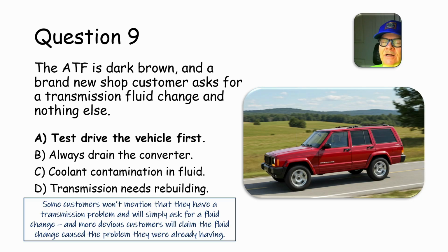And so the standard procedure we would always do before we did a transmission service, whenever I was working at the Ford place, was we would always test drive the vehicle before we ever took the transmission oil pan off. And if we test drove it and we felt a problem, we'd come back and tell the customer a transmission service is not going to fix this.